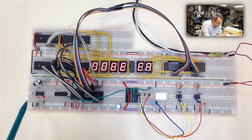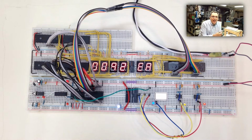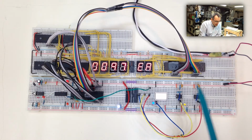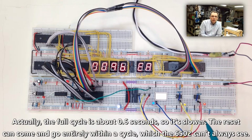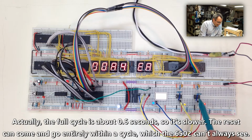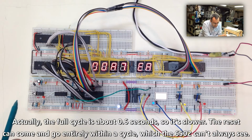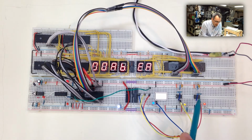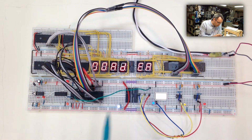The reason why this did not turn on correctly is this. This reset circuit here has an approximate 0.51 second cycle time. And our oscillator, the slow oscillator I have it hooked up to, has like a 0.46, somewhere in there, vibration time. So this guy is slightly faster than the reset circuit. Now, in this current configuration, doesn't matter. This is going to be my final reset circuit. This is not going to be my final oscillator. I'm not too worried about that.